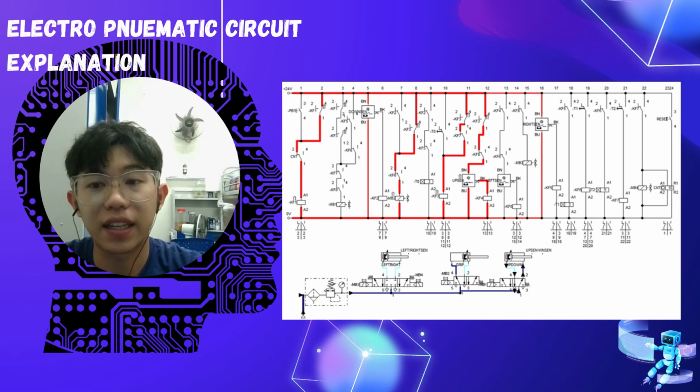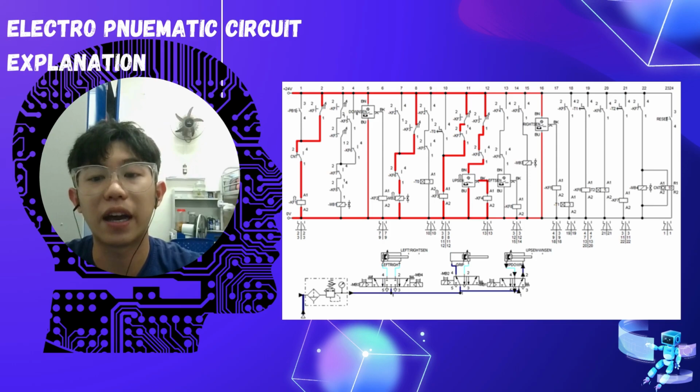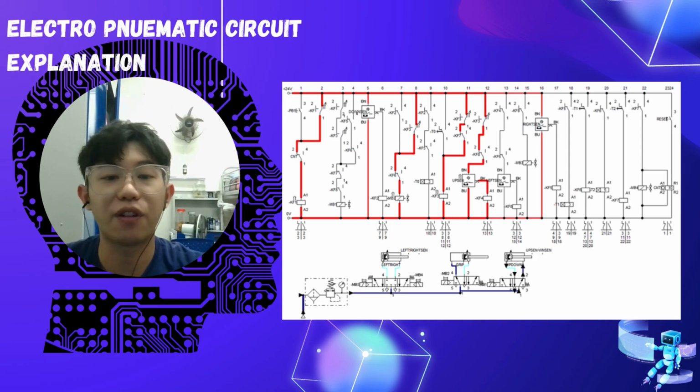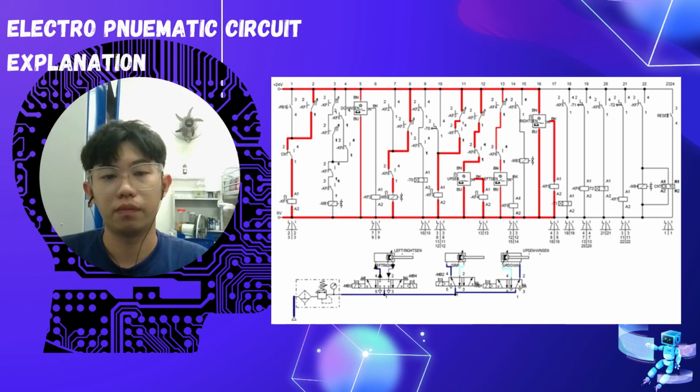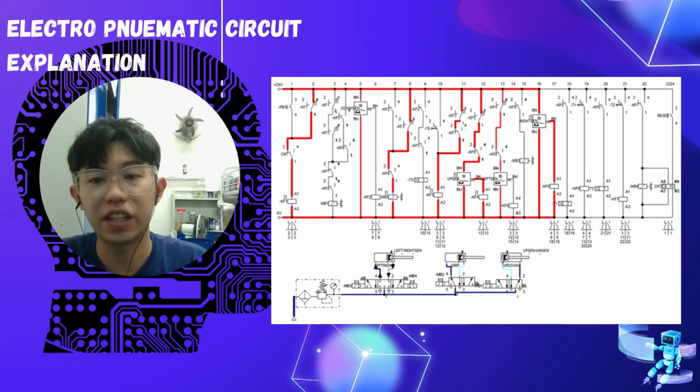The grip is still extending because the normally open contact of relay KF3 at node X is still open, and lets the current continue to flow through MB2. When the up-down arm is retracted, the up sensor is actuated. The current flows and the relay KF4 is energized. When KF4 is energized, the normally open contact of relay KF4 at node 13 is closed.